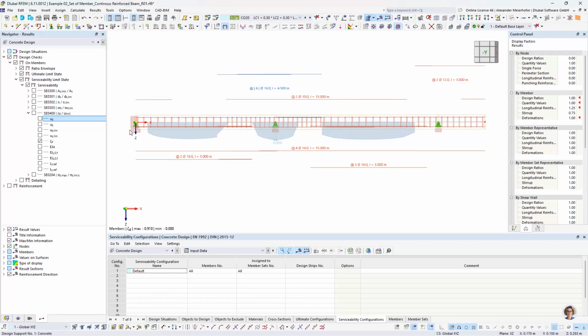Here we have nearly a total cracked state. And we can also see then the effective stiffness if we want to see it. We see here where zeta is 0, it's uncracked state, we have the full stiffness. In the crack state, we have then only the smaller stiffness, which is nearly at the cracked state. This possibility is also enabled for surfaces. It's also in the same place. You can activate it and you see then it's for surfaces.